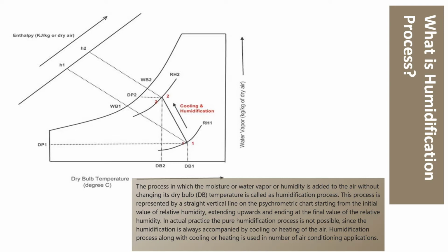In actual practice, the pure humidification process is not possible, since humidification is always accompanied by cooling or heating of the air. The humidification process, along with cooling or heating, is used in a number of air conditioning applications.